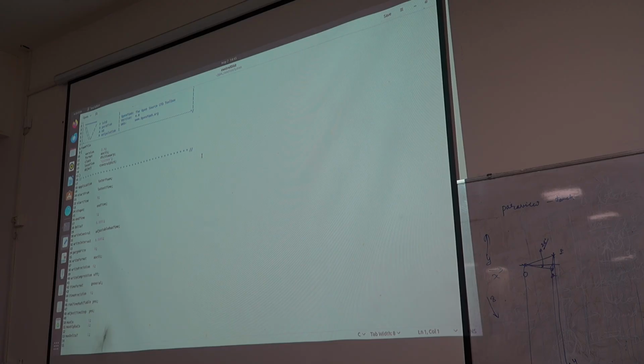You know the difference between the two, I have already communicated. So latestTime means that whatever existing folder is present, from there it will start the simulation. So the existing folder is 0, so from 0 the simulation will start. And then endTime, I want to stop my simulation at the end of 1 second, so I have written 1. What is my time step? Now you can see deltaT I have kept 0.0001, 10 to the power minus 4.